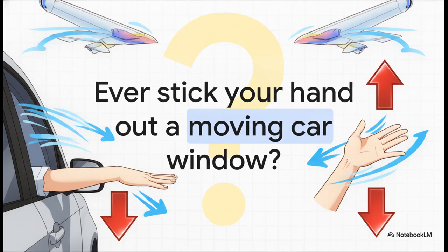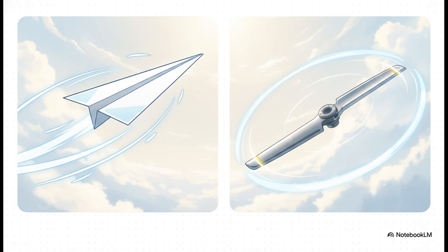This everyday experience perfectly demonstrates how the angle of attack creates what we call flow turning, deflecting the air to create a measurable directional force. And honestly, this explains exactly why flat surfaces, like those paper airplanes you folded as a kid, which are basically just flat plates, can still fly. It's the exact same deal for the symmetrical airfoils used on high-speed aircraft or helicopter rotor blades, where the upper and lower surfaces curve identically. Even without that pronounced upper camber we talked about a minute ago, these shapes can still produce lift just by changing their angle against the oncoming airflow.